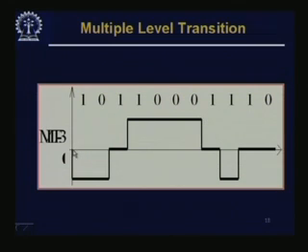Suppose with a 1 there is a transition. Now we have a transition from 0 to low level. Then for 0 there is no transition. After 0 there is a 1, so now there is a transition. Since we are at low, the only place to go is high, so we go to high. Then there is another 1, and since we are going high, we go high some more, so this goes from 0 to high. Then 3 zeros, there is no transition at all.